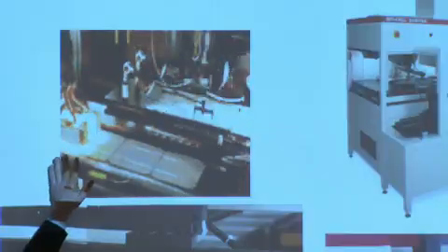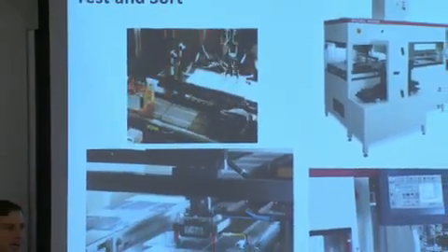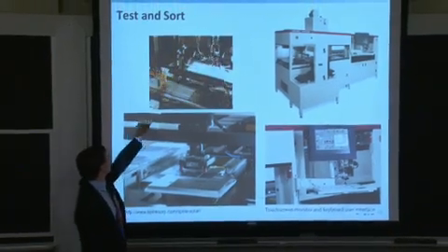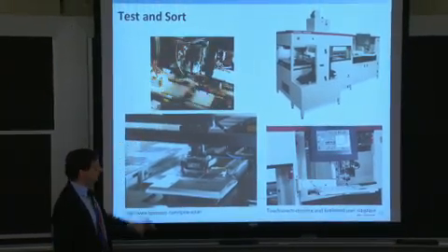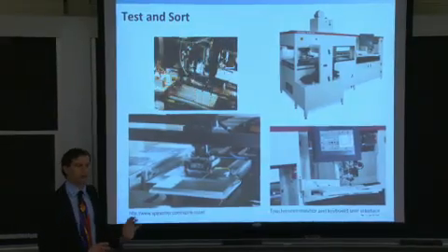So these probes right here are long, and they contain multiple contact points, and they're essentially touching the bus bars, and light flashes onto the device, simulating the sun, so simulating AM 1.5 conditions, and an IV curve is swept. I can't really tell from the photograph or from the movie right here whether the IV curve is being swept at illumination, meaning you're sweeping your voltage when the cell is illuminated, or whether the illumination intensity itself is used to vary the forward bias condition of the cell. They could be doing it in one of two ways. But most likely what they're doing is they're flashing the light, measuring the IV characteristic of the device, and then sorting the cell based on that performance.